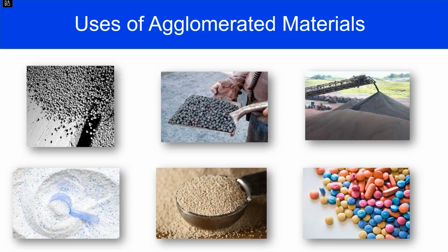And I just want to leave you with a little bit on how important the functionality of getting this size right was, so they could get the CO through, I'm sorry, not the CO2. What happened is when they put these iron ore pellets in there, the blast furnaces operated differently. They operated 5 times faster because the agglomerate allowed better flow of the carbon monoxide through the system. 80% of the blast furnaces in the United States closed down. This is a place where particle science really helped, and from a sociological aspect, it was a little hard on people.